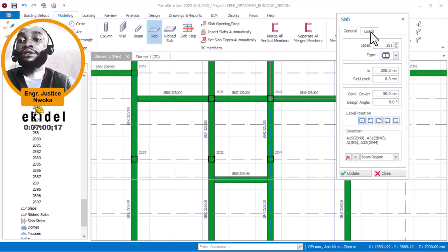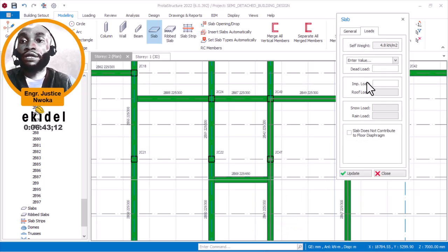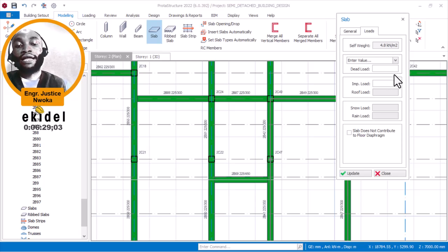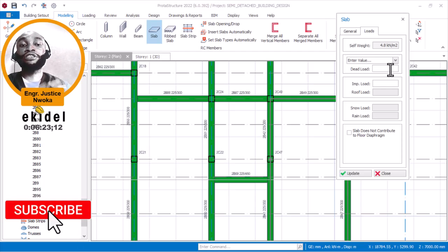Then on the loads, the load area. Now I'll begin to put in my loads, to calculate the weight of your water. Just hold on for that first; I'll show you that for now. Click on this load first. On this load, the dead load becomes the weight of the tank without water, which is the reservoir, while the live load becomes the weight of the water.